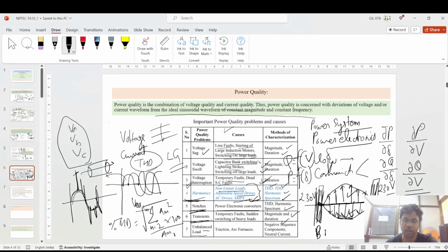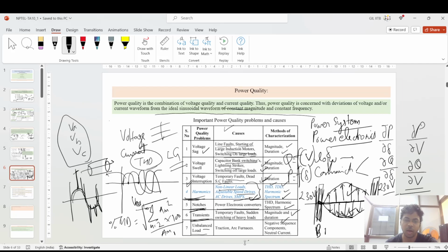And the seventh and the last is the unbalanced loading. In the distribution system, we have the three-phase system, and the single phase comes to our households. And there is a lot of mismatch between the current rating in each phase. So that creates unbalance, and because of that, your neutral wire has to be of a higher capacity to sustain this unbalanced loading in the system.